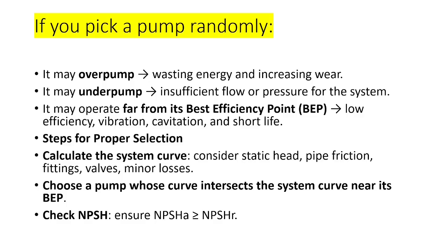If you pick a pump randomly, what will be the effects? It may overpump, wasting energy and increasing wear. It may underpump, giving insufficient flow or pressure for the system. It may operate away from its best efficiency point, causing low efficiency, vibration, cavitation and shorter life.